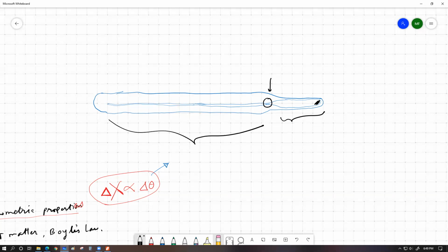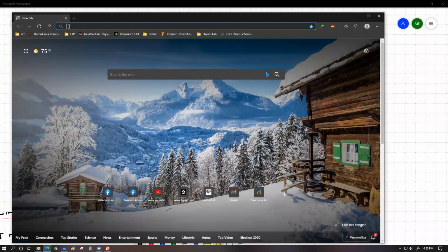Now, try to understand, let's say at a certain temperature of 0 degrees Celsius the mercury was up to here. I'm now switching to the word mercury rather than using the term liquid so that we can have a better visualization. So let's say whenever we put this whole thing within crushed ice under one atmospheric pressure, this is the height of the mercury. So we're going to give a mark over here, and then we're going to take this thermometer and put it into boiling steam. So there are two different figures for this. Let me just find this for you.